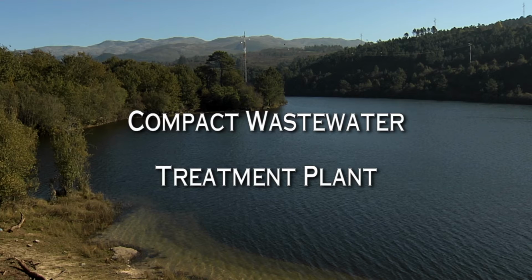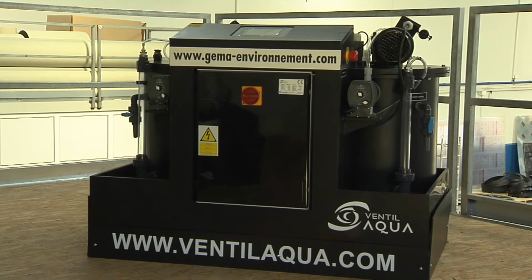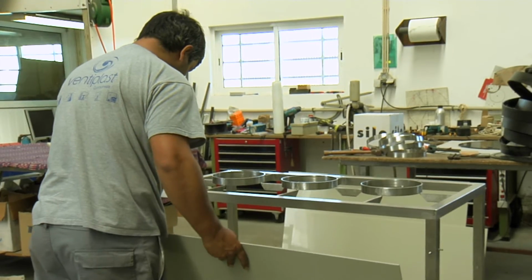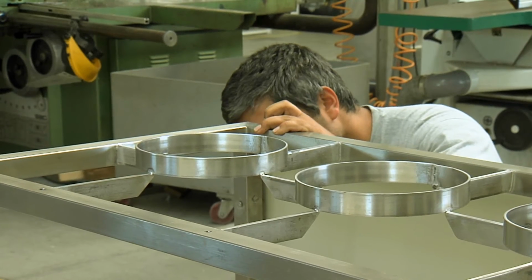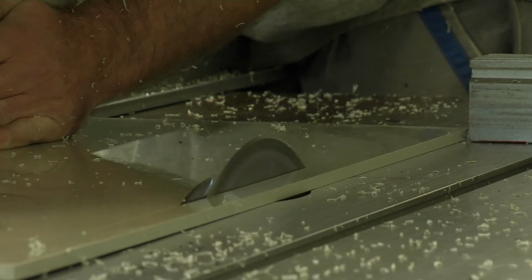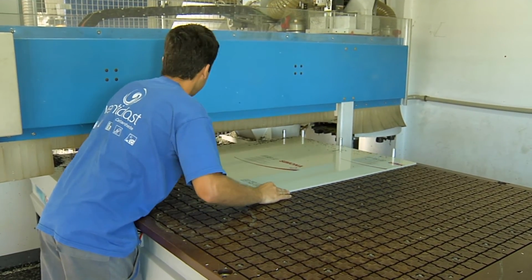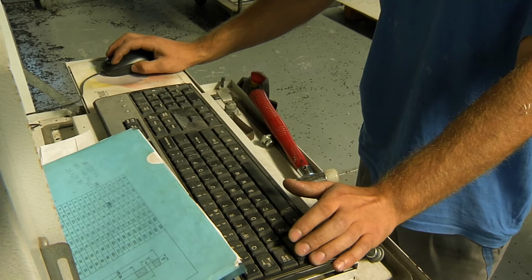Compact wastewater treatment plant. Compact wastewater treatment plants are standardized, pre-assembled systems provided with all the necessary components, such as electrical agitator, pumping system, dosing units, reactor, sedimentator, floatator, activated carbon filter and controls. Units can operate in continuous or batch process, with liquid or powder chemicals and automatic adjustment of pH in the reactor vessel.